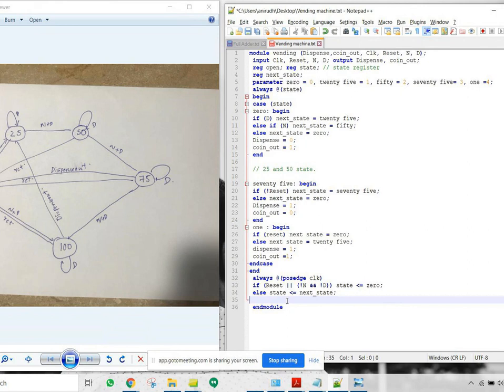From that perspective, the only input is currency, which is 25 cents multiples. Or in your case, you have assumed that there could be a dollar bill also. If you look at the state diagram, you say from state 0, you can go directly to 100 state, right? How can you go from 0 to 100 state in one step? By inserting a dollar bill directly. Right. So that is another input you will have in your case.